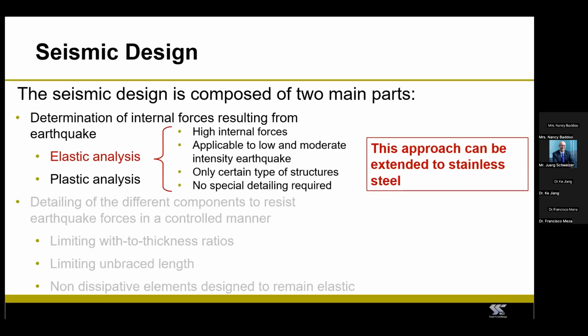The elastic analysis is the most conservative approach because in this case, it is assumed that the structure remains elastic during the earthquake. The internal forces in the structures are very large. So this approach is only applicable to situations in which the structure is subject to low or moderate intensity earthquakes, and it is only applicable to specific types of structures.